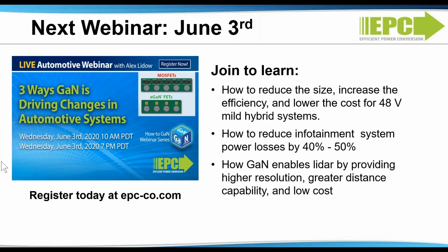You showed the 3-level converter efficiency is better than the 2-phase converter. How good is the transient performance of the 3-level versus the 2-phase? The transient performance is actually better for the multi-level converter, because the multi-level converter actually has a buck converter as its bottom stage, and this buck converter is going into an inductor that is much lower inductance, like 2 microhenries versus 10 microhenries for the multi-phase.